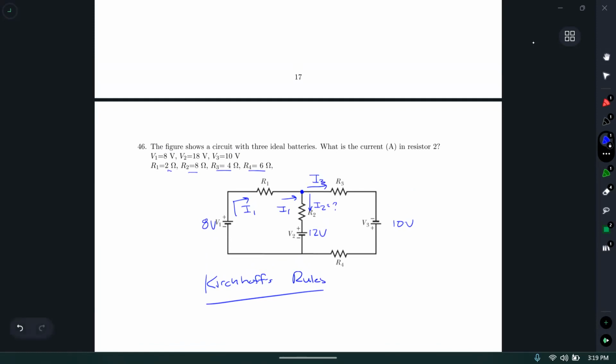Okay, I now need to follow all of my currents to make sure I don't end up doing more work than I need to figure out what currents are what. So this I3, if I keep following it around, I'm going to see that it's eventually going to reach this bottom junction, because once it goes through this branch, it's only got that one way to go.